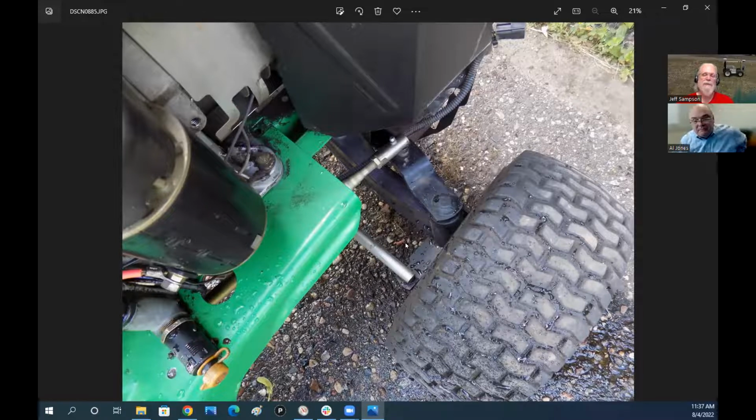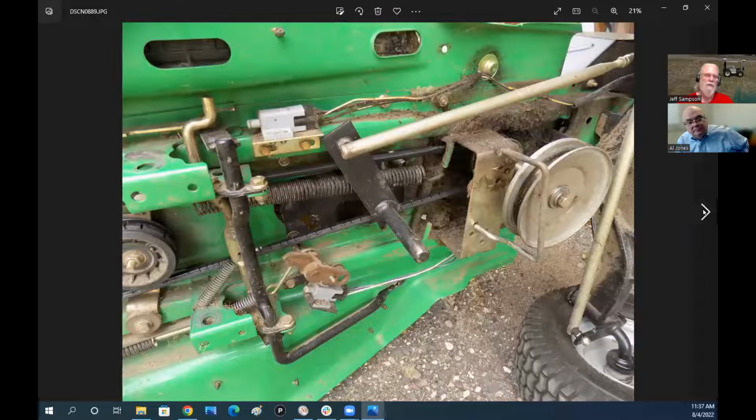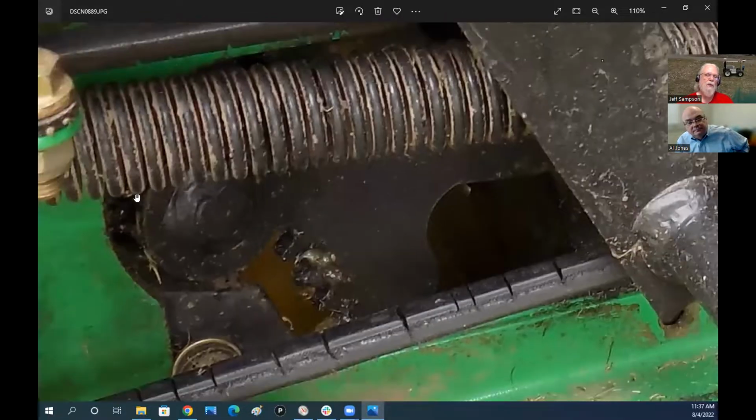And it seems to be working, other than my steering's looser than it should be, because over the years I didn't keep the center pivot greased, and I didn't keep my wheels greased. So everything's a little bit sloppy, but it does indeed work. And as I say, when I run the motor in reverse direction, I think it's the slight slot between this gear and the little gear here, so it clunks as you move back and forth.